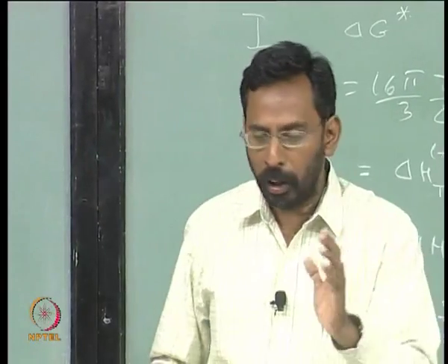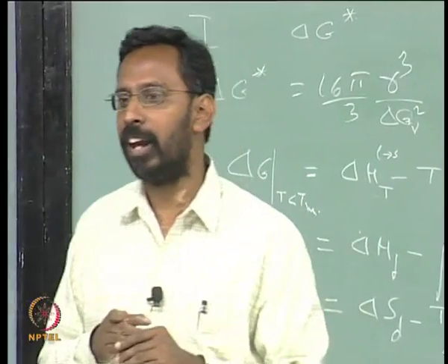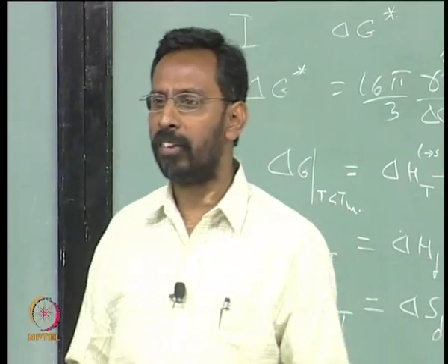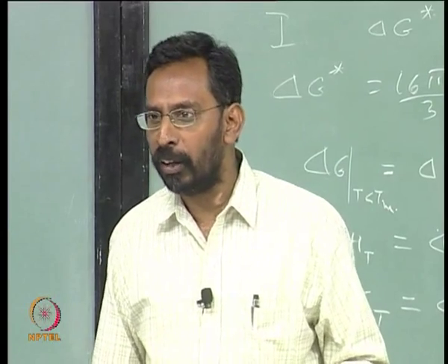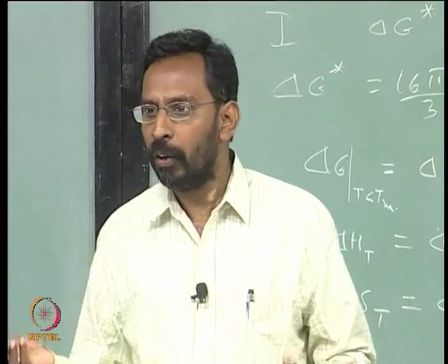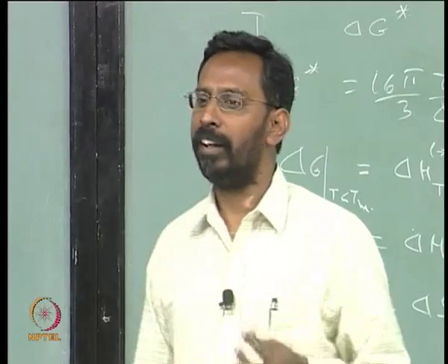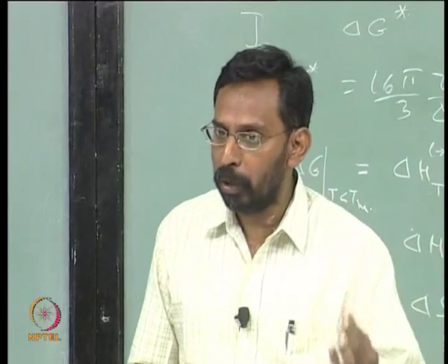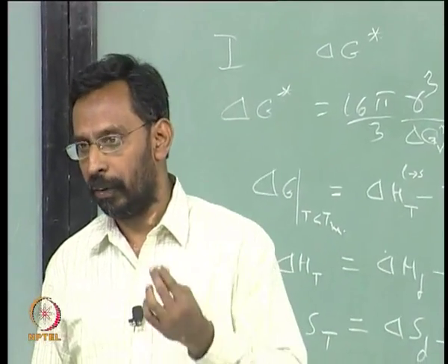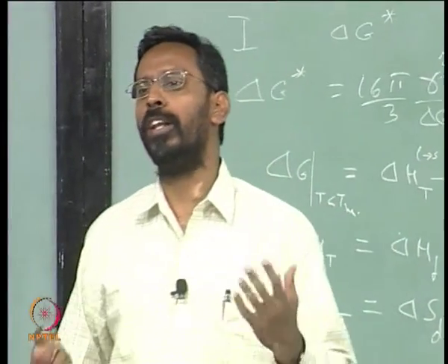So, the moment I say nano aluminum and its melting point, let us say is 600 degrees centigrade, if I say I am measuring the heat capacity at 600 degrees centigrade for the liquid, that is a stable liquid already, it is not a metastable liquid, it is not an undercooled liquid. And then if you are measuring that, it is of no use to you, because that is a different type of material. I am talking of a bulk liquid undercooled to below the melting point, and I am measuring the Cp below the melting point and maintaining that liquid as a liquid during this measurement.